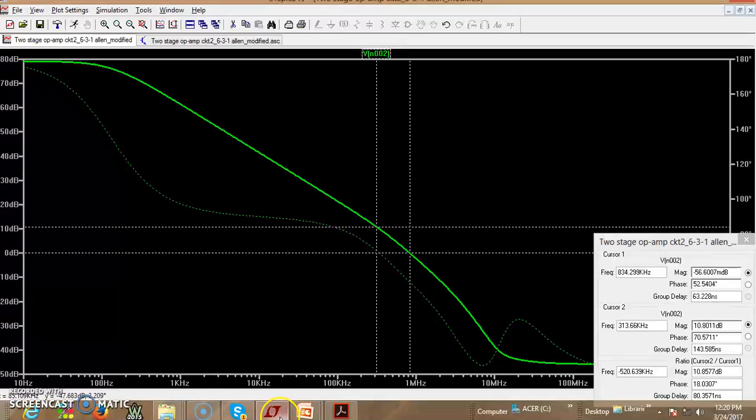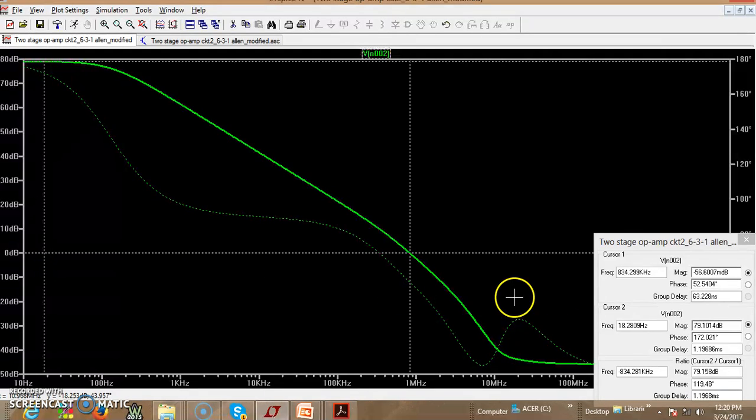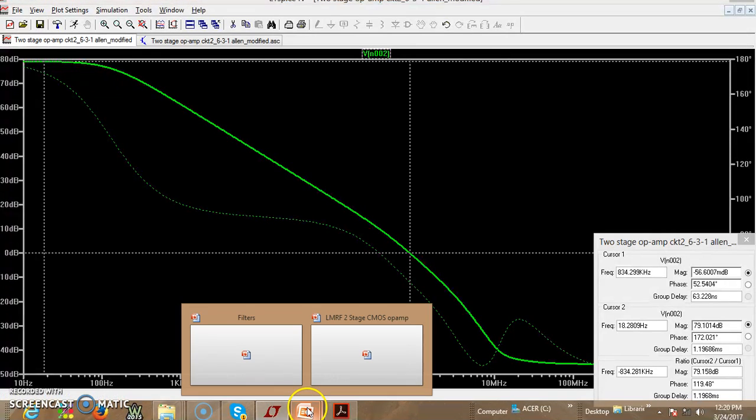So let us find out what is the gain now. So gain is almost close to 80 dBs. This is the gain. So gain is almost 79.1 dBs. You can actually verify the gain of this particular circuit using gm1 R1 into gm1 gm2 divided by, so we have in the denominator the current of I5 and the lambdas of M.